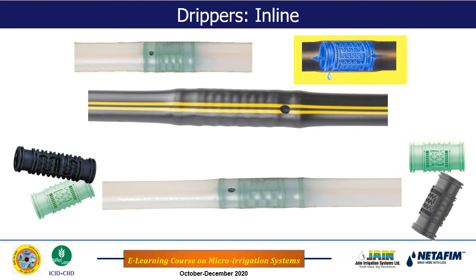Orchard plantations have a life of more than 10 years, 20 years and so on. But anyway, the life of these laterals and drippers is not more than 7 years. Okay, so for the orchard plantation, we can lay the laterals along with the online emitters, and we don't have to remove those actually. For that purpose, we can use the online kind of emitters when we use the system for orchard plantation. This also doesn't mean that for orchards we shouldn't use the inline kind of emitters. We can use them, but those are a bit more expensive compared to the online emitters.